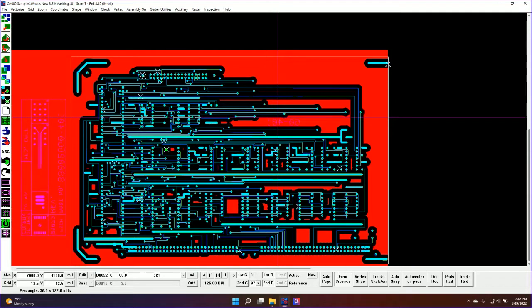So, that is a really simple way to use masking. It doesn't require any Gerber editing, nothing. It's just an additional function you can run. And remember, you can program keyboard macros. So you can use a hotkey that both runs the inspection, and then as soon as the inspection completes, will run that mask function automatically. So all your operator needs to do is hit a hotkey and then enter the threshold.